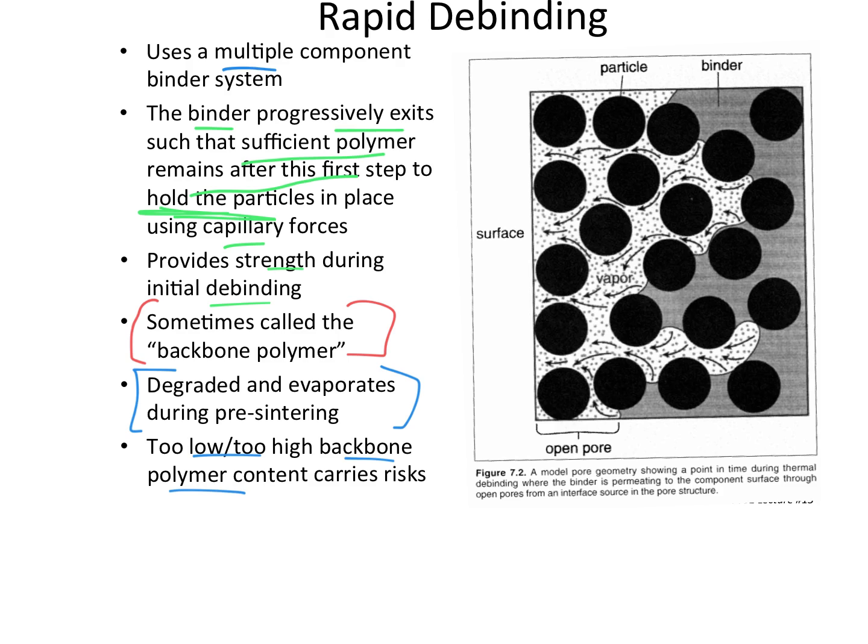With metals, an easy thing is that they can absorb carbon when everything is said and done. So the sintered part can form, and it can also gobble up the carbon, put it into the metallurgical structure, and generate carbides, which has advantages in terms of properties, as you guys now know. It'll stop dislocations from moving. So you can do this, but you have to make sure you don't do too much of it, all right?